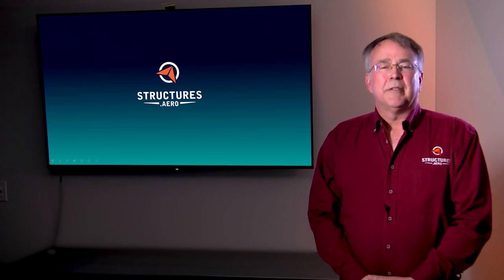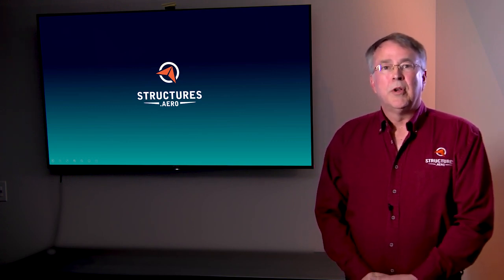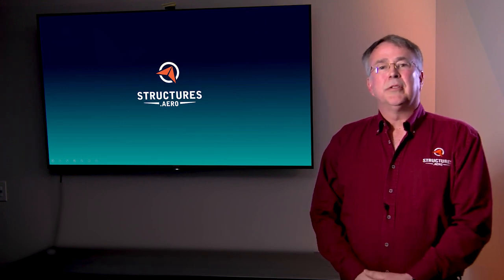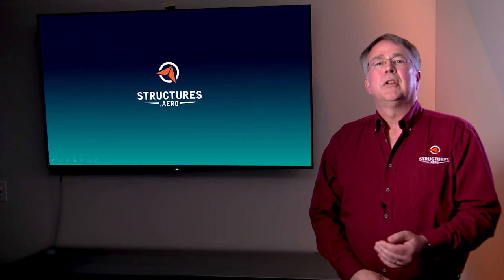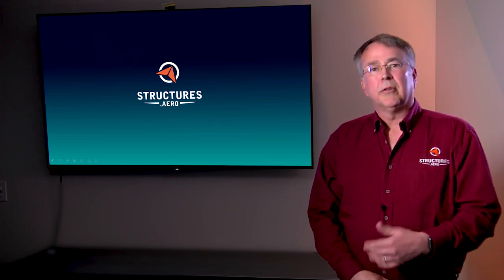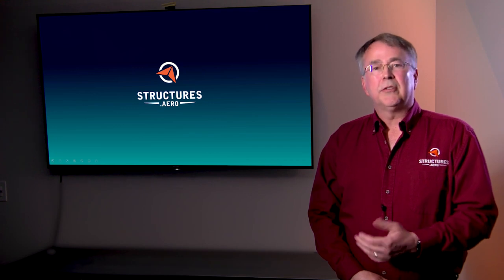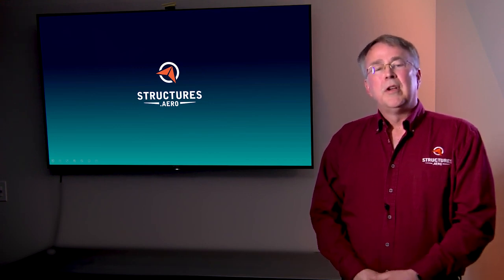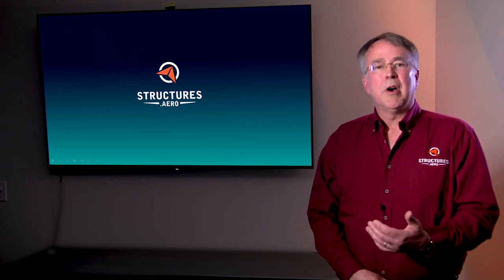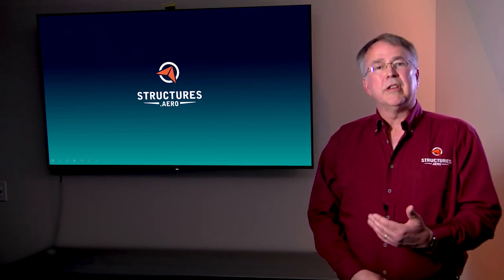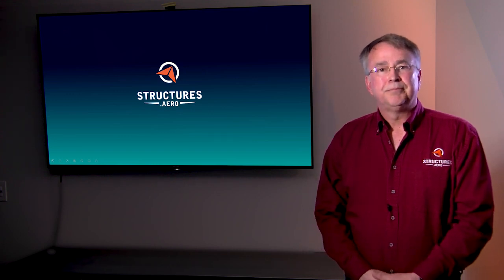The features coming out in the new version of Femap 2021 that we're most looking forward to are the mesh-on-mesh capabilities. We frequently get models that require us to remesh, and we don't always have geometry. So having the ability to generate a new mesh based on an old mesh is going to be very helpful for us. The new mesh propagation commands are similar, where we have to deal with models where the geometry just isn't very easy to work with, and having the new features are going to be very helpful.